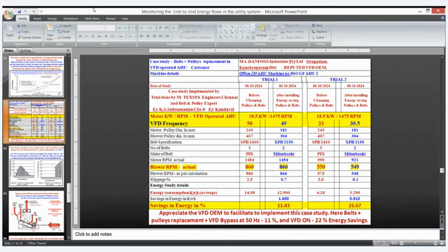The pulleys also need to be changed every 40,000 hours. This is mandatory. The OEM has to educate the end user. So this is an area which we are even trying to take to the Bureau of Energy Efficiency, and it is a universal phenomenon. I'm not trying to talk about the affinity loss of the blowers here. I am trying to talk about the torque that is delivered by the motor and the torque that is demanded by the blower. There is a gap.